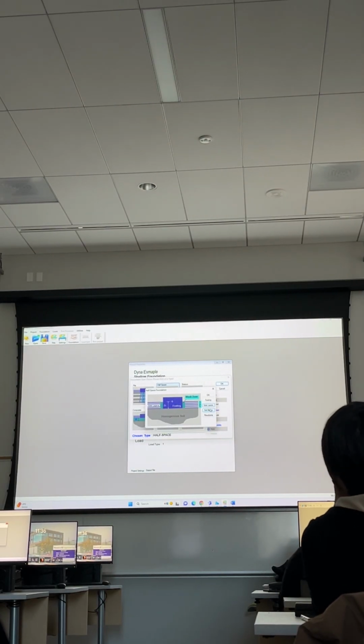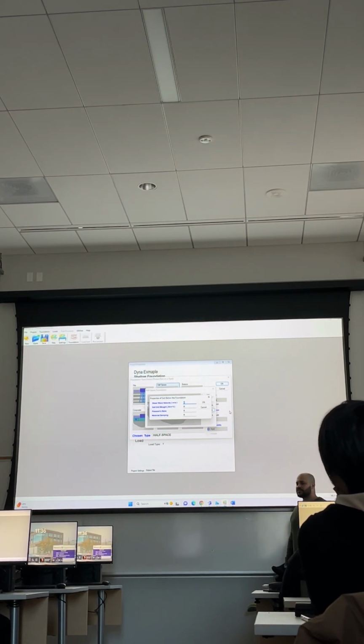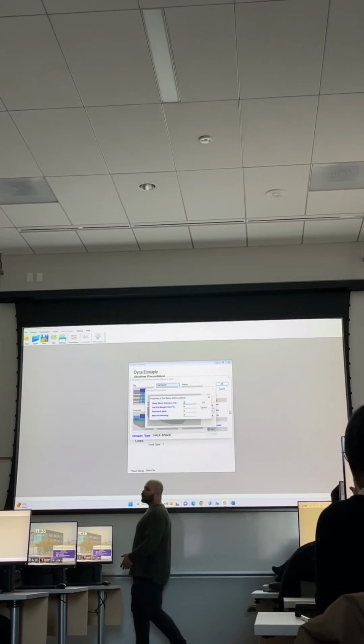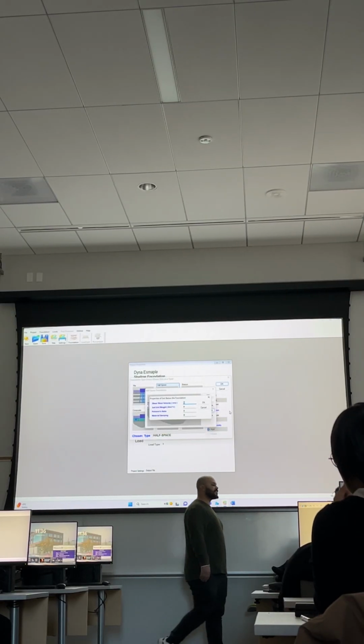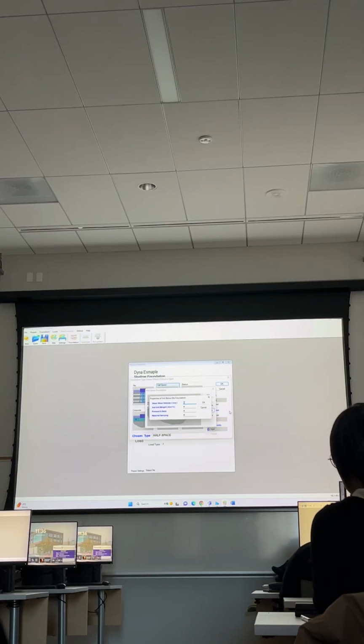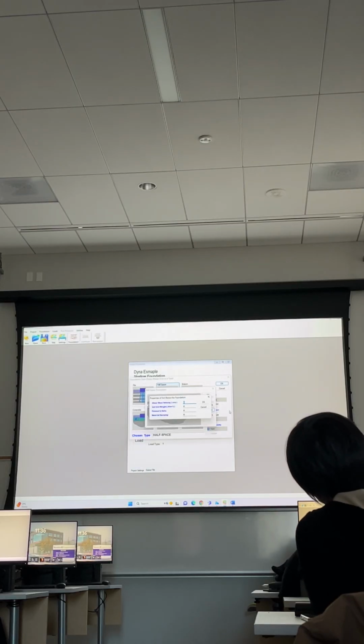Okay. Next step is the soil below. Soil below is the soil below the foundation, and as you know, this is the half space area. So if you have layered soil, you can calculate the best estimation or the average of this soil to get the shear wave velocity. You did this step in assignment 1, right?